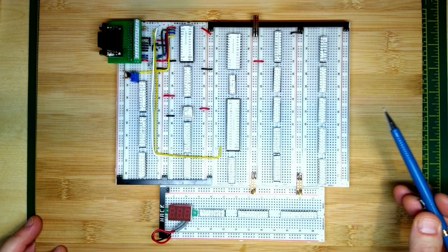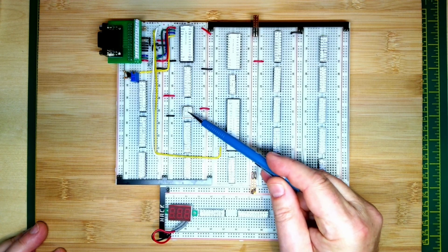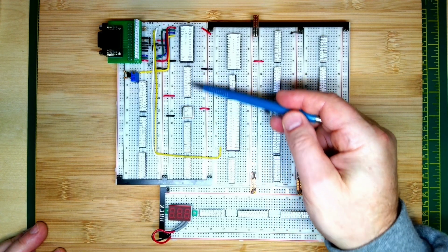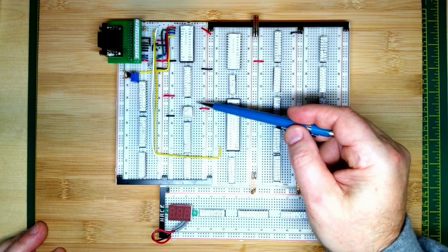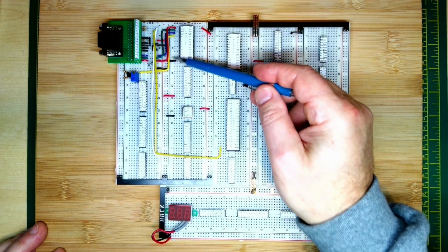So now what we're going to need to do is to sort out the clock. This is the 25 megahertz crystal here. This is the clock PLD for which we're going to be feeding the 25 megahertz in, and then the dot clock output is just going to be going in up here.